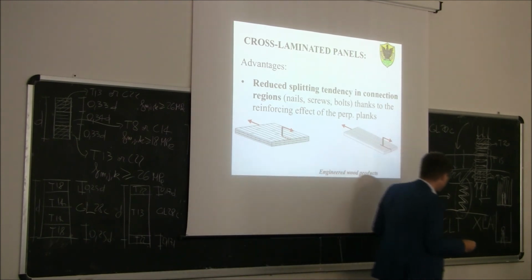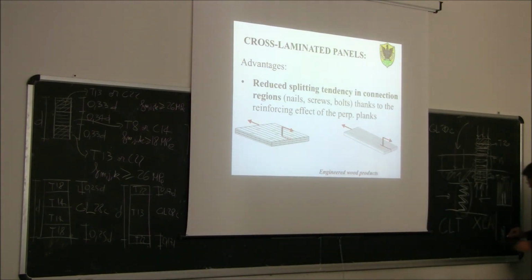The perpendicular layer is loaded by these tensile stresses parallel to the grain. Parallel to the grain, the strength is much higher compared to the strength that the two outer layers have perpendicular to the grain. So in this case, this kind of failure cannot occur. It will never occur because the secondary stresses are much lower.